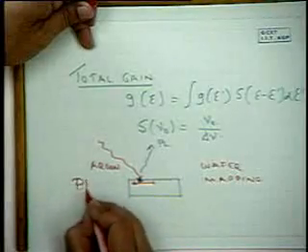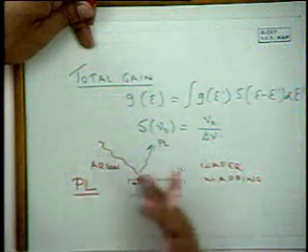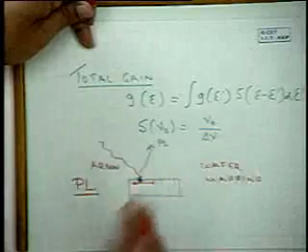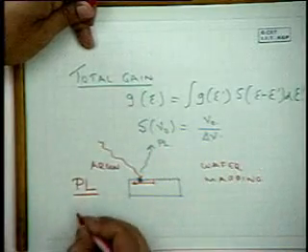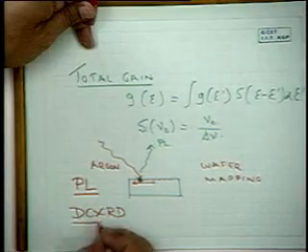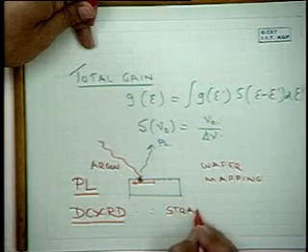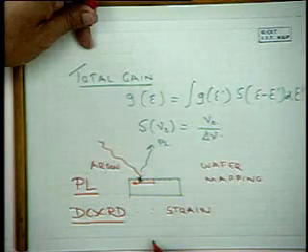So one method is experimentally through PL. That will obviously tell you about composition. If there's a composition fluctuation, then nu 0 will change. The other is DC XRD, double crystal X-ray, which will tell us about strain. The lattice parameter changes from point to point, and then the X-ray diffraction pattern will change.